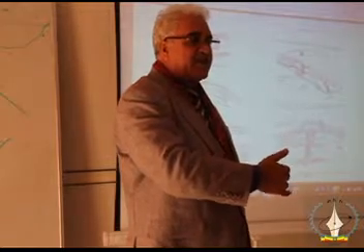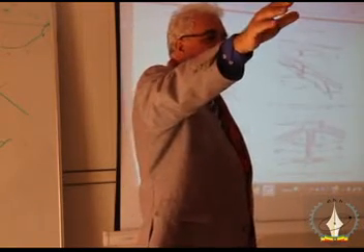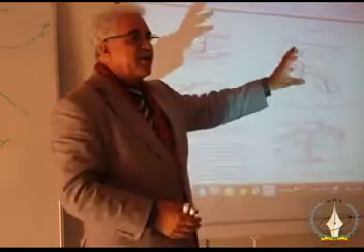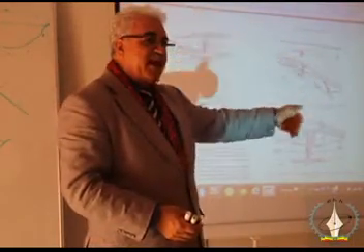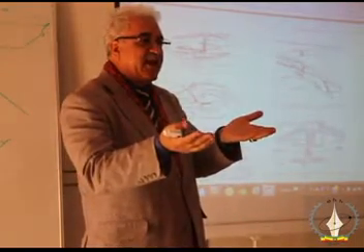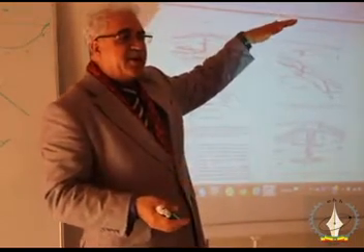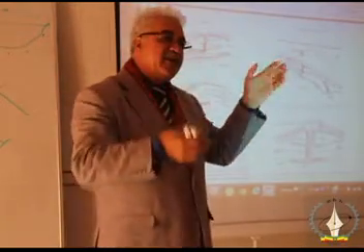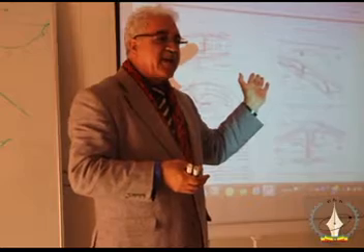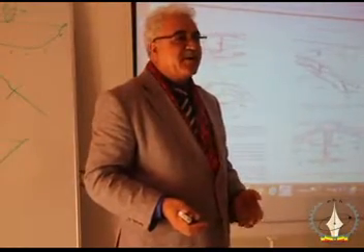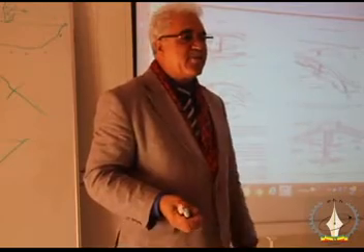Once the ship is in, they close the gate at the downstream side. Then they release a water valve from the upstream side to fill this basin up to the level of the water at the upstream side. When it is at that level, they open the gate at the upstream side so the ship can flow and navigate further upstream.